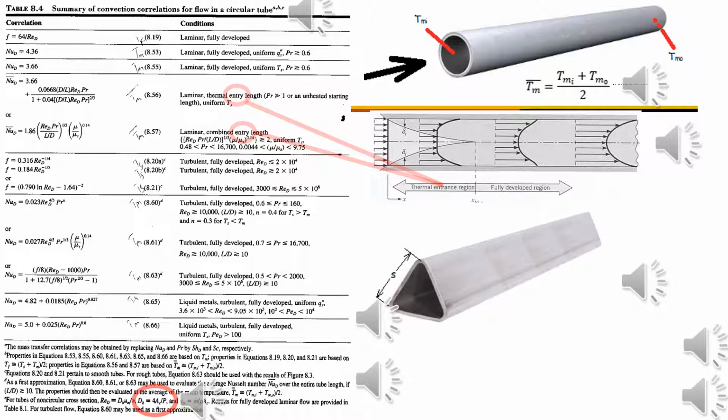The area of a triangle is half base times height. In the diagram, the base has length, s, while the height may be determined from Pythagoras' law. The wetted perimeter is the length, in the cross-section, where the fluid touches the tube wall. You can see that the fluid touches all 3 walls of the tube, so the wetted perimeter will be 3 times s.